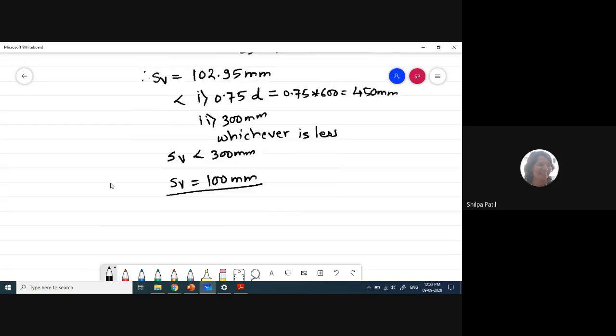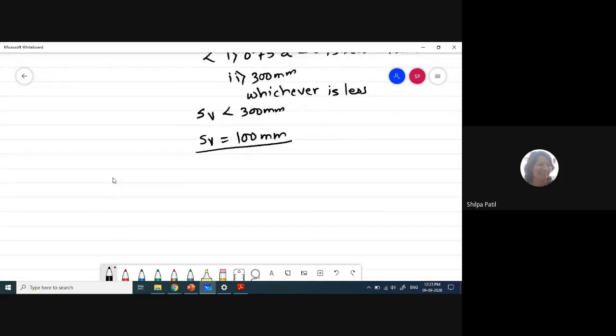Okay, so write down one statement now. Here we have actually completed the design for shear reinforcement. We have calculated the area required and we have also calculated the spacing between the stirrups. For zone 1 only, we have to design for remaining 2 zones also.